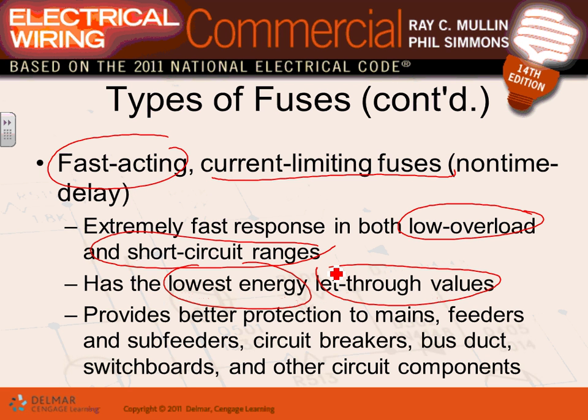Better protection for feeders, sub-feeders, circuit breakers, if you have to protect a circuit breaker, like bigger circuit breakers, ducts, switchgears, and so forth. Fast acting fuses, you don't typically put in motors. You put dual element time delay fuses on motors because of the inrush.